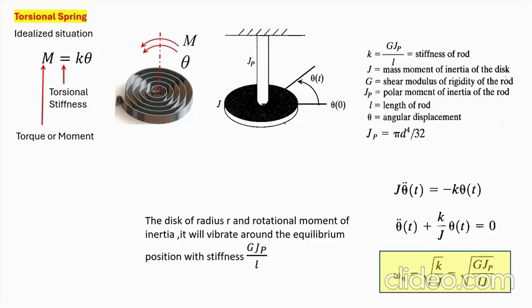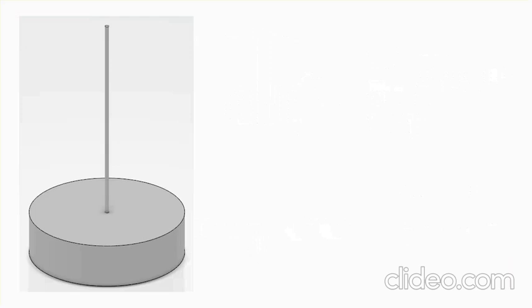What I'm going to do is model this particular geometry for you. However, remember, I'm not going to model the shaft. What I do is calculate the torsional stiffness of the shaft and then use it later on along with the disk that you see there. The details of the dimensions of the shaft are given here. So that gives you a torsional stiffness as you see up there.